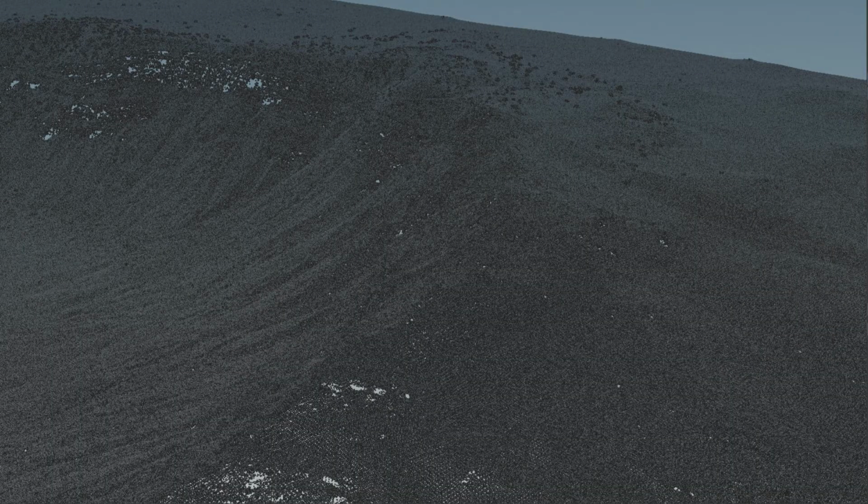Let's look at what the Lidar data actually is, and then we'll talk about one of the popular GIS applications that you'd use to work with data. If we look at this image, what you see are the points that the Lidar system gathers into a point cloud representing the ranged surface. Geographical Lidar is often gathered with an airborne system, with an airplane shooting a laser towards the ground and measuring how long it takes the laser to bounce back. Depending on the intervals, you'll get a dense or a sparse point cloud.